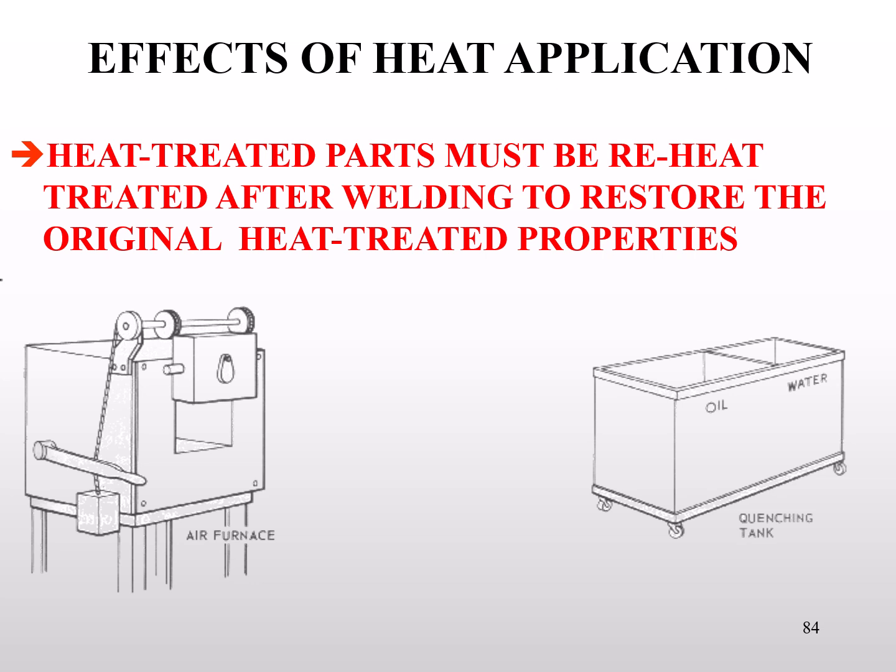I can't see into the future and say you will or won't work at one of these places, but I can say this. If it's a heat-treated weld, then it's going to have to go to one of those places to be made. So how does that affect us as the mechanic on the scene? Well, that simply means we take the part off, we ship it to that repair station. They do the repairs, they do the paperwork to make it airworthy, then they ship it back and we reinstall it.